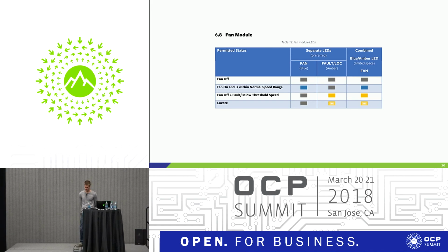And in the event that you're a system manufacturer and you want to sell to OCP community members, as well as some of your traditional folks that expect green and amber, you can have programmable RGB LEDs and have an LED controller sit there. And now the difference between those two BOMs that I described is really just a firmware difference. Now, there are some logistical nightmares in making sure that the right gear lands in the right spot, but that certainly can be overcome. That doesn't apply to the connectors, because for the physical LEDs, there are only two control lines to it.